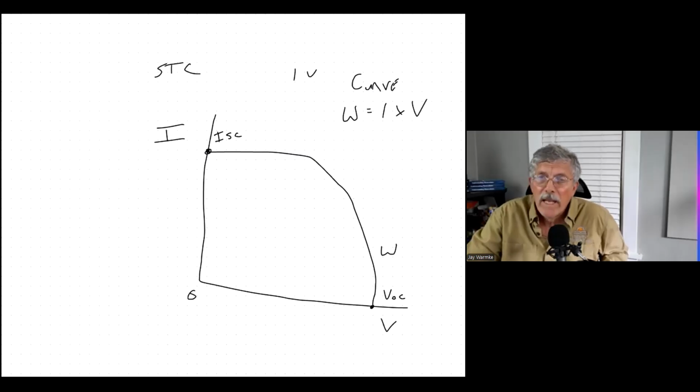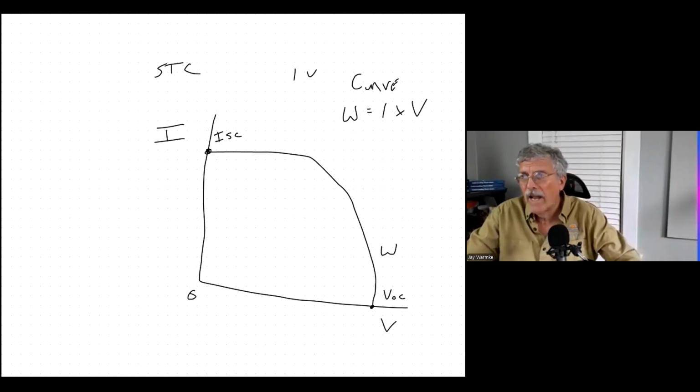So how did they come up with that? Well, a group of middle-aged white guys who met in Paris just said, we need a number. How about today? So they go outside and they go, all right, we're at sea level, about 1,000 watts per square meter. It's about 77 degrees, which is 25 degrees Celsius. And in Northern Europe, North America, the sun passes through about 1.5 atmospheres.